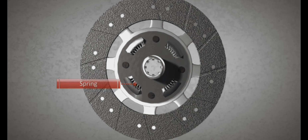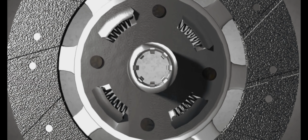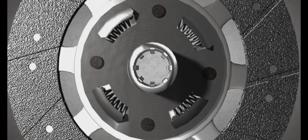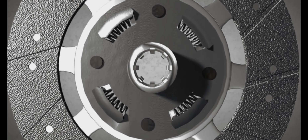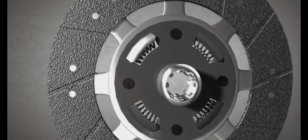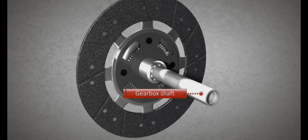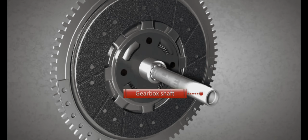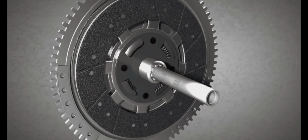In general, cars for daily use are equipped with clutches that feature springs to dampen shudder, to achieve easy operation, and to reduce the impact to the gearbox at the engagement. The clutch disc is connected to the gearbox through the gearbox shaft. Consequently, the wheels of the vehicle only rotate when the flywheel is in contact with the clutch disc.